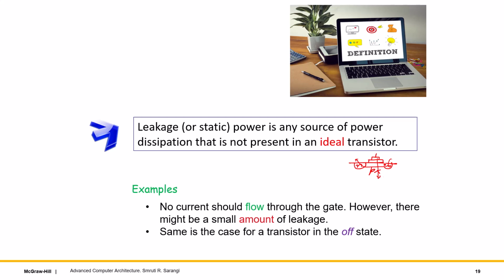But the fact is that there is nothing ideal in practice. It is a theoretical concept. Anything which is assumed to be ideal, there is still a very teeny amount of current that is flowing through it, and this small amount of current is known as leakage or the static current. If you integrate the leakage power, or static power, across the billions of transistors in the circuit, it's actually not that small. It turns out to be anywhere between 20 to 40% of the overall power dissipation, depending upon the technology, of course. But leakage then becomes substantial.